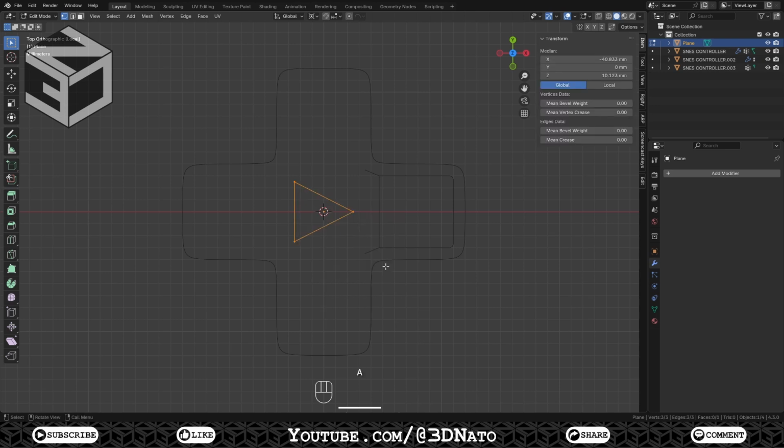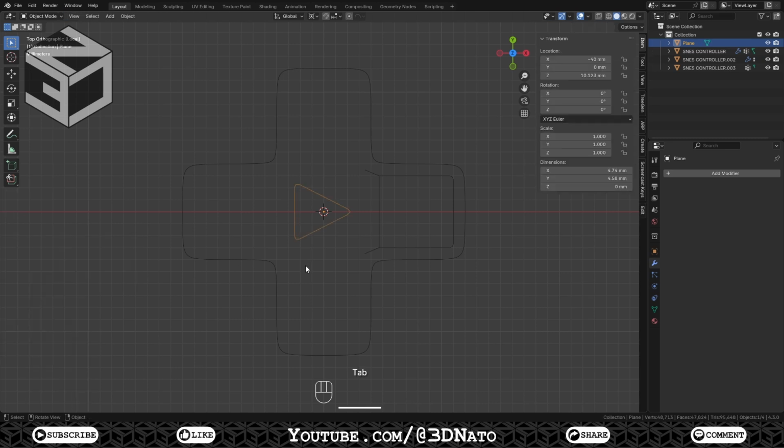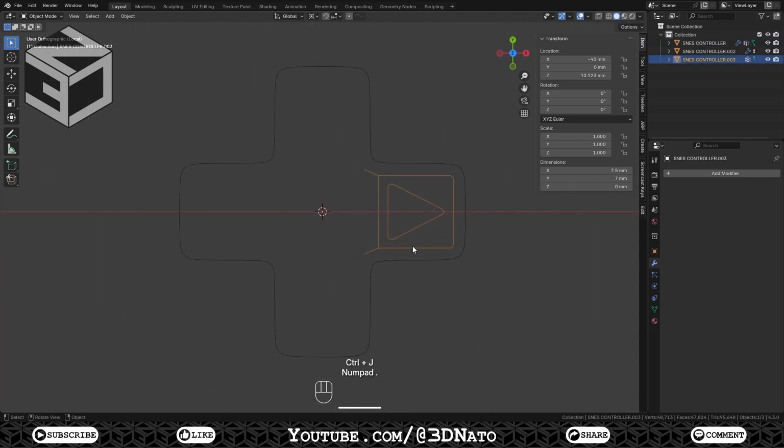Press A to select all, Ctrl+B to bevel, change effect to vertices, width to 0.5 mm and segments to 2. Press Tab to exit edit mode, G to move, X to lock axis, type 8 and enter to confirm. Shift select the D-pad mesh and press Ctrl+J to join.